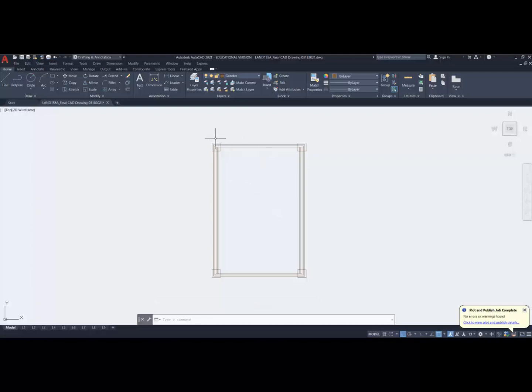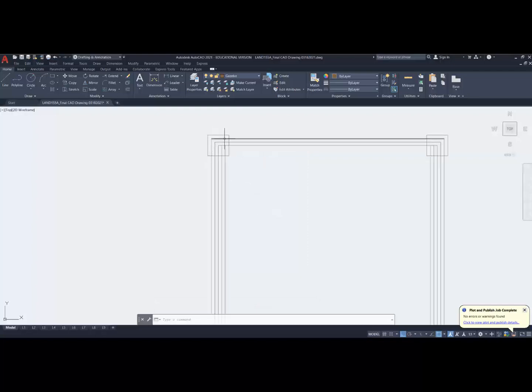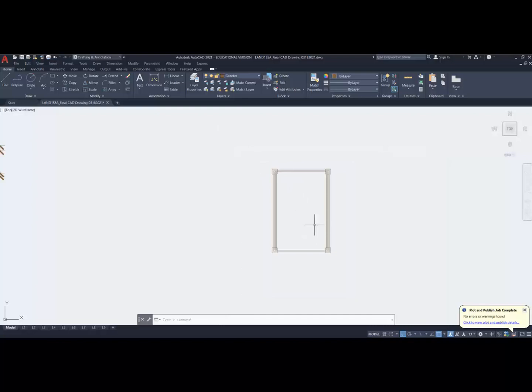And we will cut the post and we'll notch it out so this outer part of the post will actually go up and beyond the actual beam itself. But we'll take a look at that later. So now I have to determine what size ceiling I want. The roof overhang contributes to that ceiling, not to the span of the joist, but to the ceiling itself and how big that ceiling is going to look.